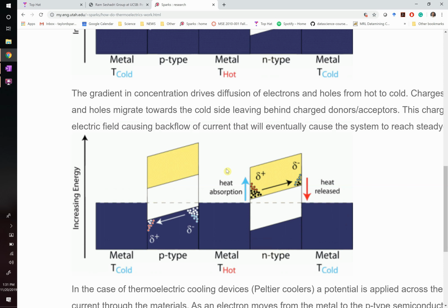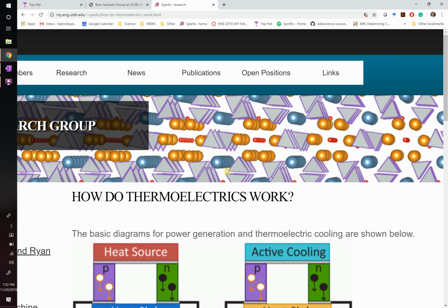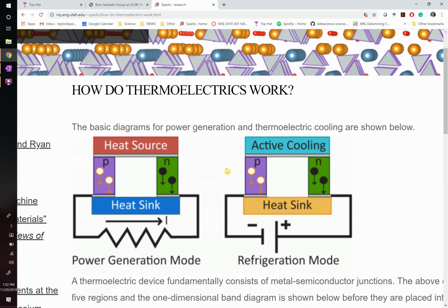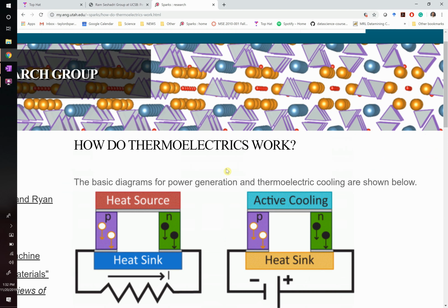Jaden? Why couldn't you do it with just one P-type or one N-type? Because they're both creating a potential difference in voltage. So you have to have a circuit. These devices have to exist as circuits. So if you just had one of them, which side would be hot? Right? Let's say we get rid of the N, and we just take metal and connect it down to here, we skip this thing. The problem is you'd have an imbalanced charge. You wouldn't have charge balance.